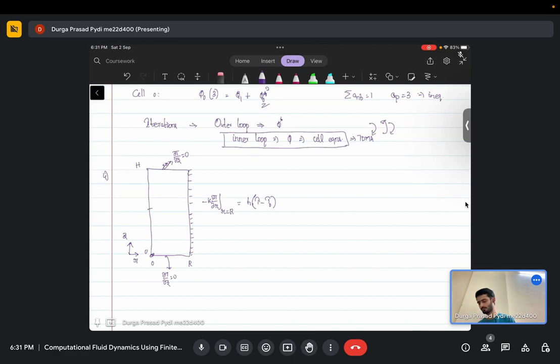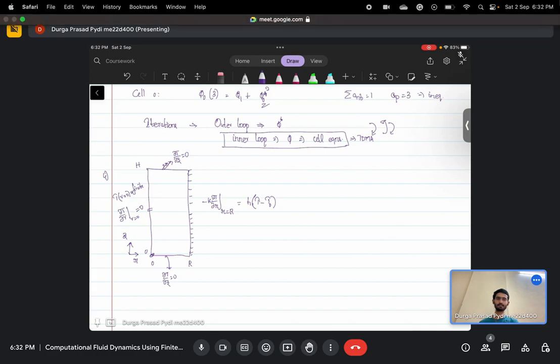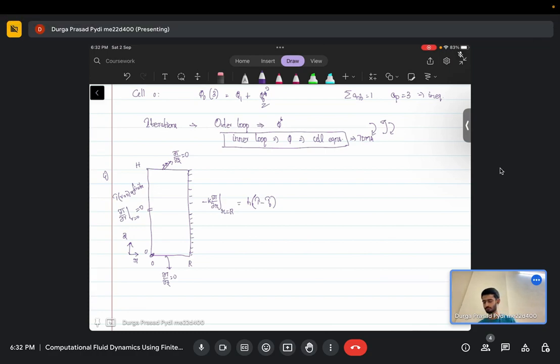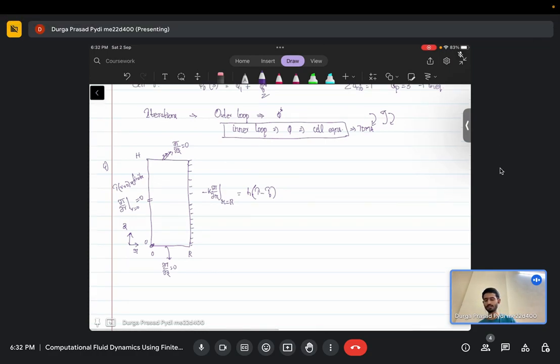And for an axisymmetric case, what is the boundary condition at the center line? You have a symmetry, so you can either say T at R equal to 0 is finite, or because of the axisymmetric condition, you just say the temperature is the maximum at the center line, so del T with respect to R is 0. So these are my boundary conditions.